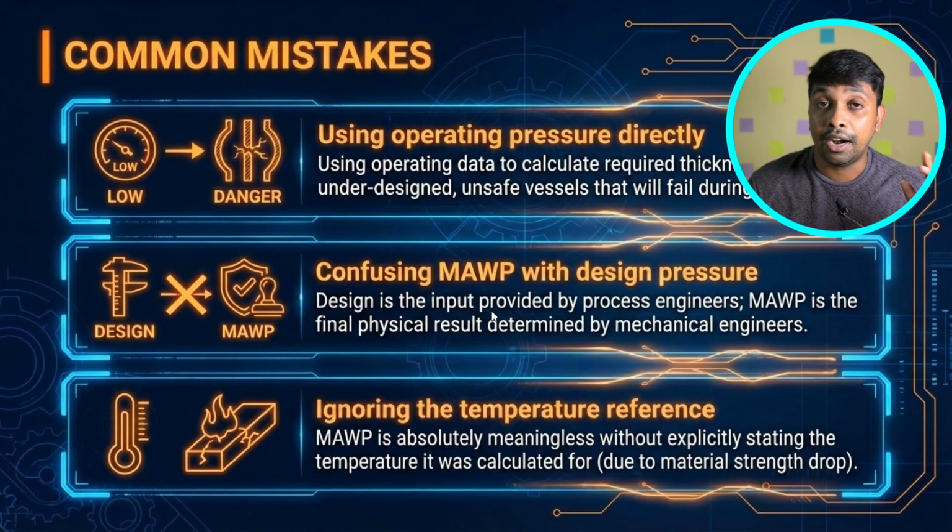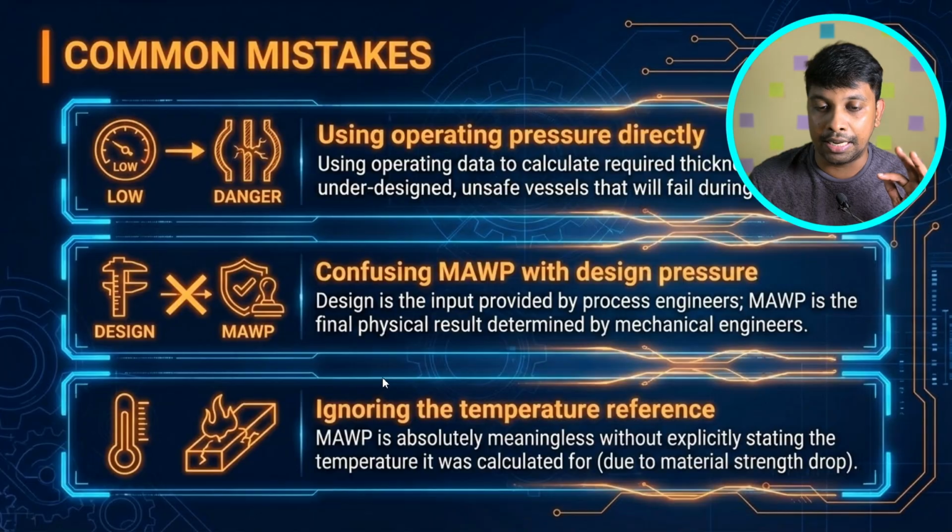And the second one is confusing MAWP and design pressure. Those are completely different. As I already explained, MAWP is normally higher than the design pressure. That is one of the confusions.